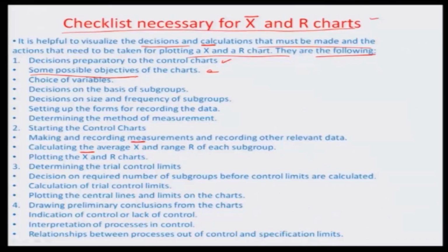That could be a function of the wear at which the cutter may degrade, or the change of dimensions resulting from poor machining conditions, or maybe vibration and chatter. So there is a requirement of plotting the measurements with the objective of measuring the slot width of the particular milling system which is in place. So that starts the process.